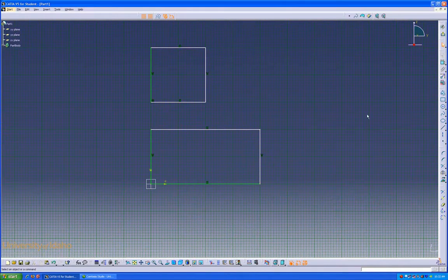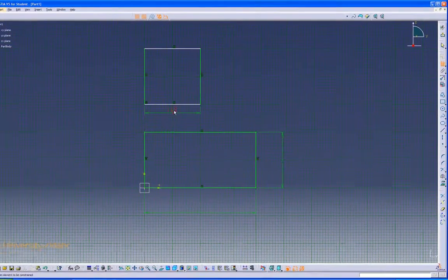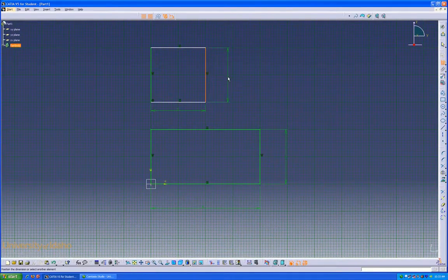To finish dimensioning these, click on the Constraint button and then click on the line you'd like dimensioned. If you'd like to dimension more than one line, double-click, and you can dimension several. To get out of the double-click, either re-click the icon or press the Escape button twice.